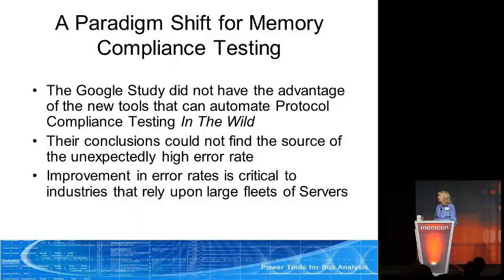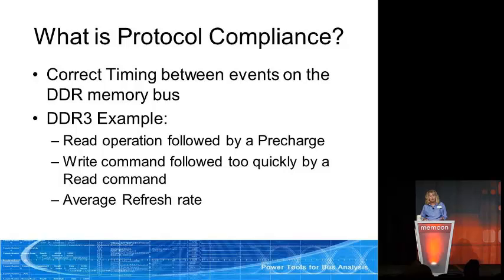So first of all, let's take a look at what protocol compliance is. What am I talking about when I use the phrase protocol compliance? Well, it's the correct timing between events on the memory bus. From my perspective, that means events that occur on clock tick boundaries. So we didn't take a look at, let's say, setup or hold times, which would be whether the data is valid prior to the clock edge or after the clock edge. That was a little bit more of an SI type of issue. So we look at timing between events.